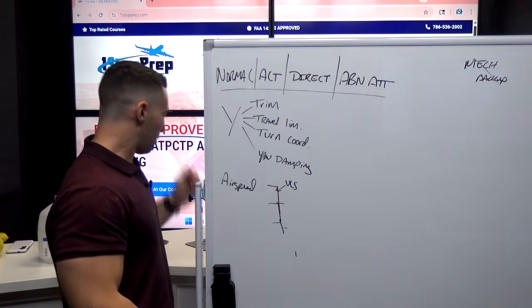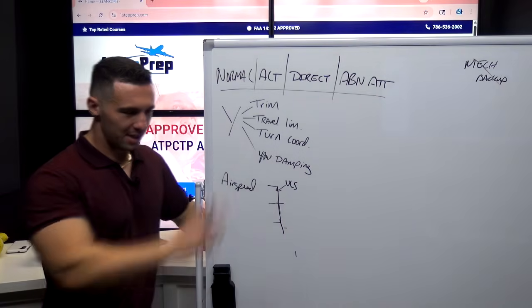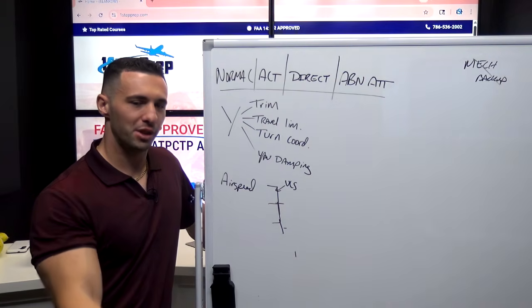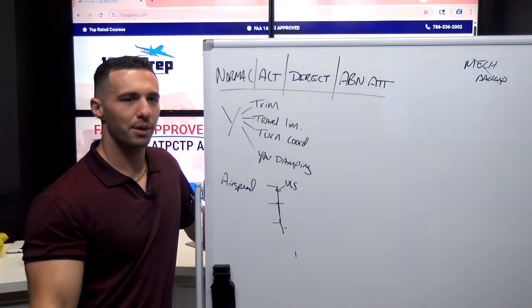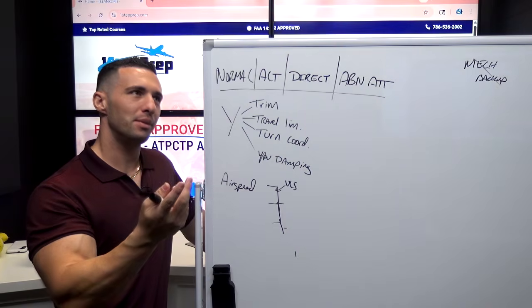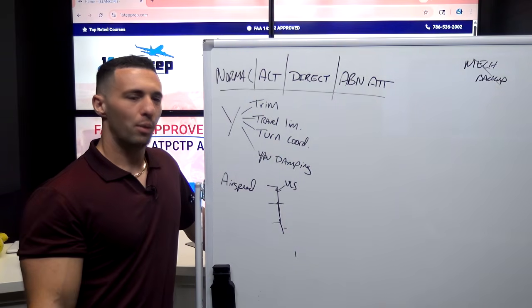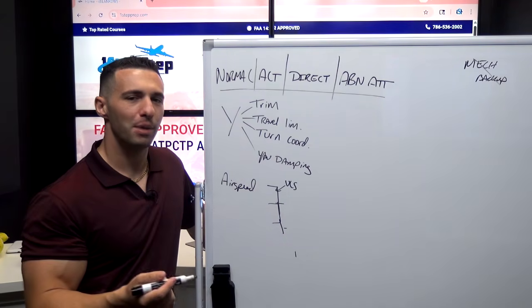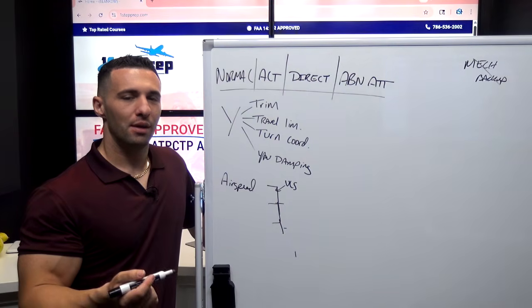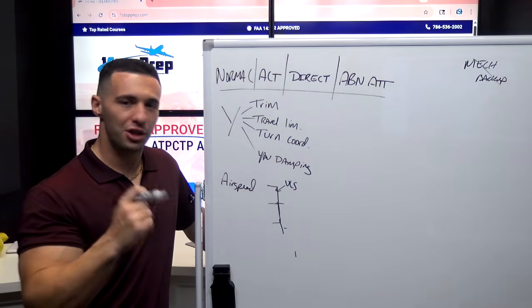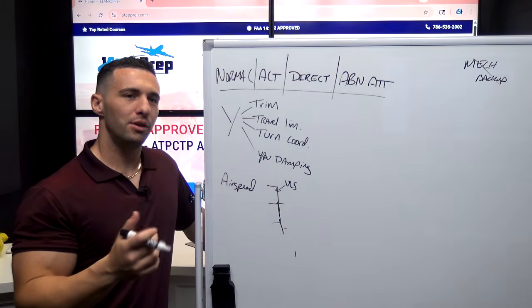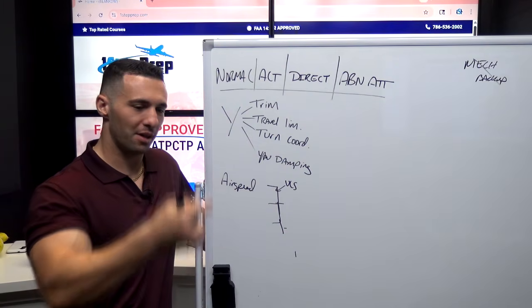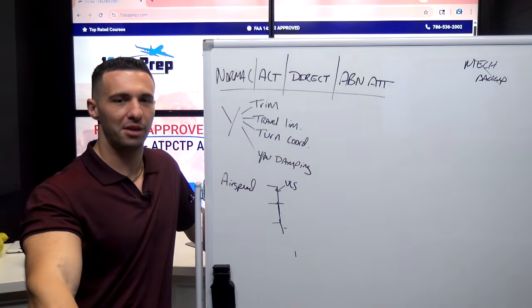By the way, I just got an email, a question, somebody asking how come VLS on the tape looks different than the VLS on the perf approach page? So they're looking at the perf approach and they could see VLS is 135 or whatever. Then they look at the airspeed tape and the number disagrees. Well, remember VLS on the tape, driven by the FAC, is dynamic, so it moves with flap, spoiler, and G loading. So it's possible that you were either in a turn, you were pulling some Gs, you had a flap configuration or the spoiler deployed, and the VLS is sliding up and down, and it will differ from what you see in the perf approach page, right?